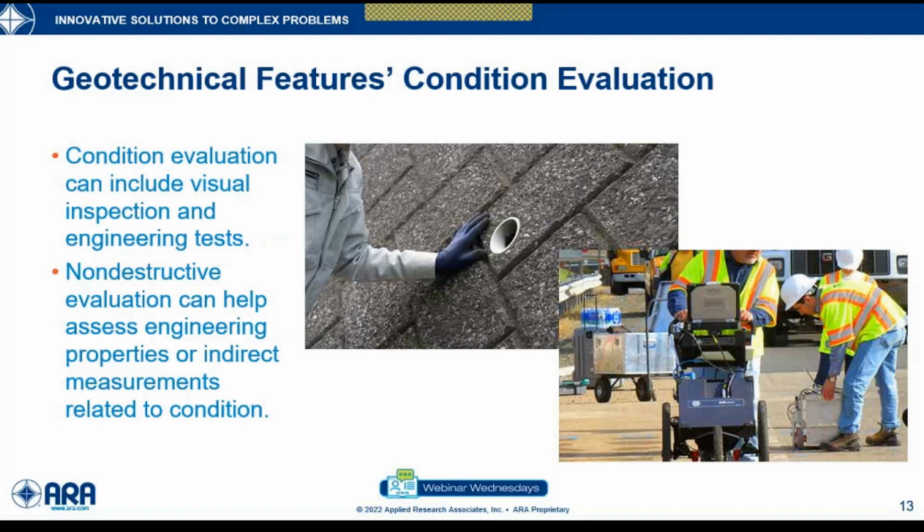There are, for example, visual inspection processes out there for agencies. They have manuals on how to inspect certain assets, for example, culverts and retaining structures. Not all agencies at the same time have these manuals or procedures, not necessarily, but visual inspection would be one approach to do it. Another approach would be to acquire actual engineering measurements, in the sense that they measure, for example, strength, deformations, or other in situ properties.